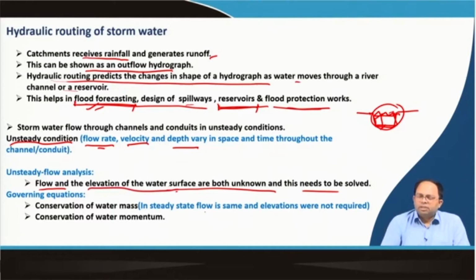That means the depth of flow would also be different at different parts of the section. Earlier, in a particular sewer section, we were considering the depth of flow like half full or maybe 2/3 full or 1/3 full. So, we were considering a particular fixed depth of flow, but now it is not fixed. That is the difference from steady state flow.